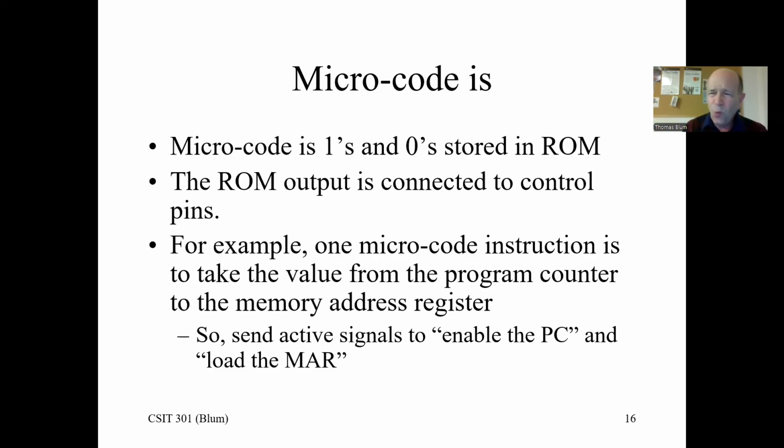and really think about them as ones and zeros to sort of talk to the hardware and get this action of loading the accumulator accomplished. So we said we had all these pieces in our architecture, and all of those pieces had things they could do, like take something off the bus, which was load, put something on the bus, which was enable, and they just had to be told to do it by that pin on the device that gets it to do its thing. And so we're going to start imagining the ones and zeros of telling something to perform its action or to just rest.